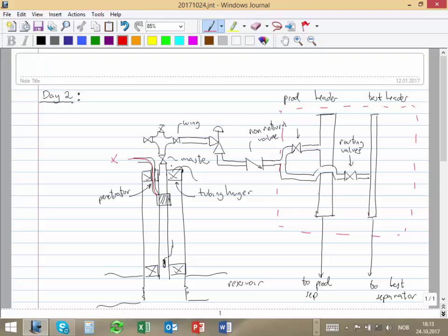And when we are onshore, really, we don't usually have any need to do pigging. But when we are subsea, then you want to send a pig. If you send a very small pig and then it comes to a big area, the fluid will just bypass it, and it won't flow. Or if you send a very big pig and then it comes into a small area, it won't be able to pass. It will just be stuck in place.